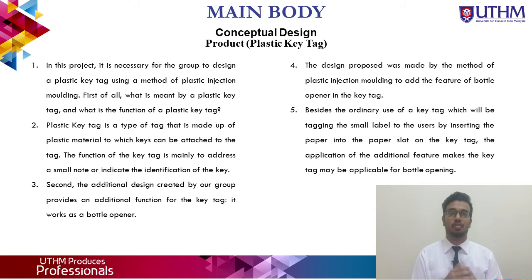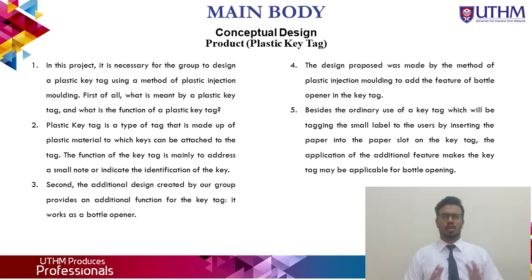Hi, so as for my part, it is the conceptual design. So conceptual design consists of 3 parts, which is the product that refers to the plastic key tag, and then next will be the mold cavity, which refers to the workpiece, then followed by the electrode, which refers to the tool. So as for the product plastic key tag, in this project it is necessary for our group to design a plastic key tag using a method of plastic injection molding.